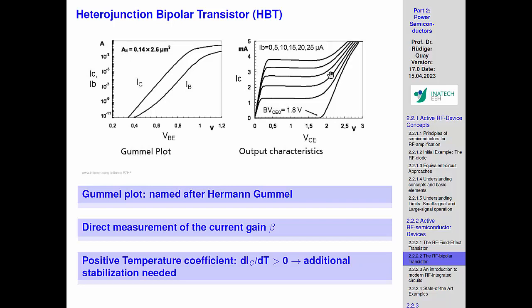It's a very simple trick, because if you put a slight resistance to the base in the right way, just the right value, if it's heating up, this resistance will increase a bit and will control the base current so that you're moving a bit down here. So if you adjust this correctly, you have to think of it. If you miss that, then the whole thing blows through the roof. If you get it, then you're in good shape, because then you can make use of these nice characteristics of the device.